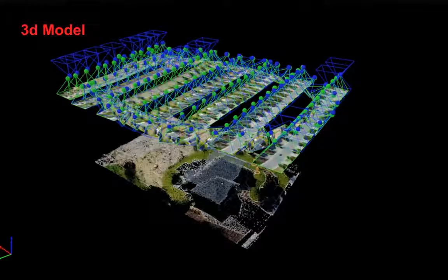You can go out and put ground control points, like printing out a hash mark on paper and laying that out at particular intervals. That will actually help Pix4D process things, because it has a very clearly delineated ground point, but it's not necessary to do.